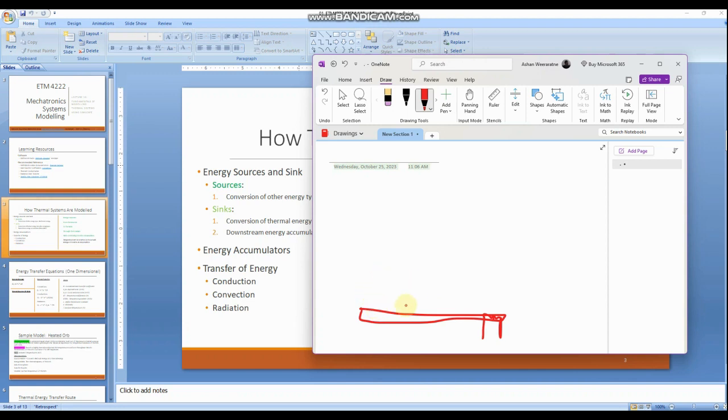And if you remember your gas laws, gases with higher temperature will have lesser density, and when a portion of gas has lesser density than its surroundings, it will float. It means the gas over here would expand to a higher volume, its density would be less, and it would float upwards. And what was initially at the top would move downwards, and upon moving downwards, it would gain heat from the plate.